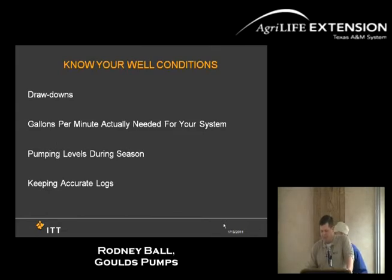You need to know the gallons a minute that you need for your system, whether it be your pivot or drip irrigation. You need to understand what your needs are, because if you oversize a pump, there are many different things you can run into, which I'll talk about in a minute. But you need to know your pumping level, and be aware of what your well logs are doing and so forth.